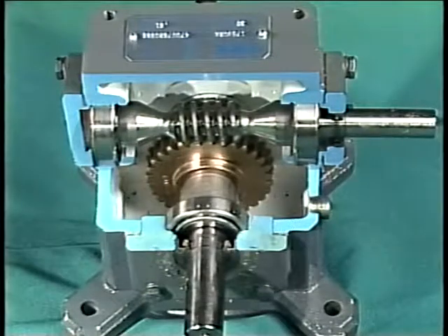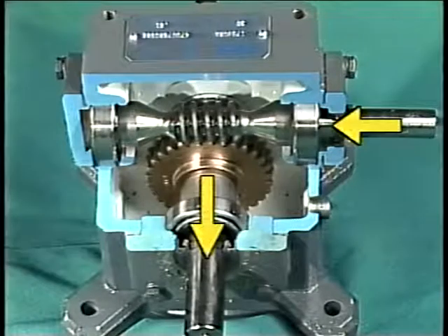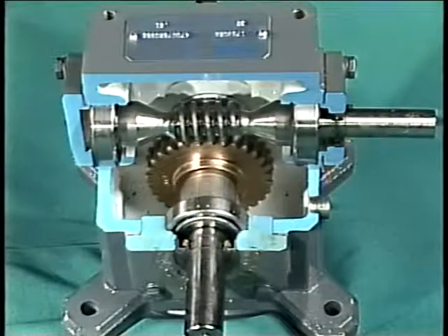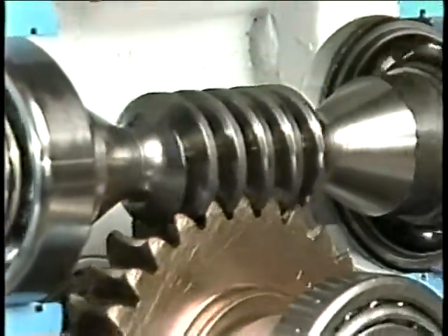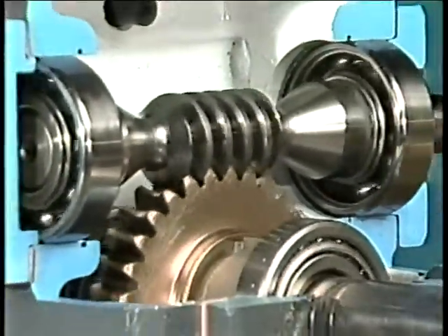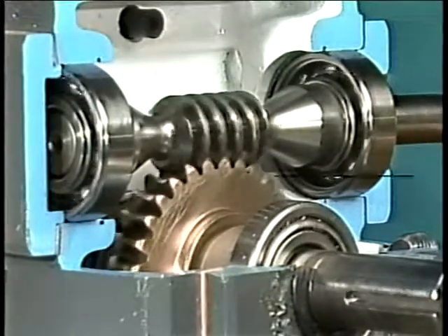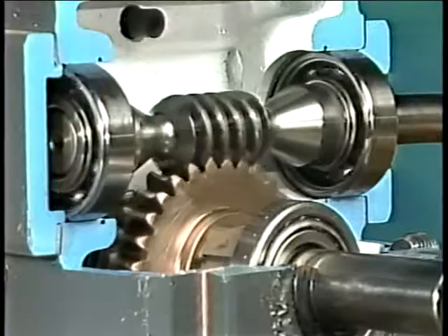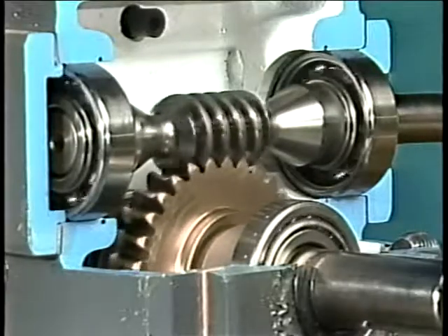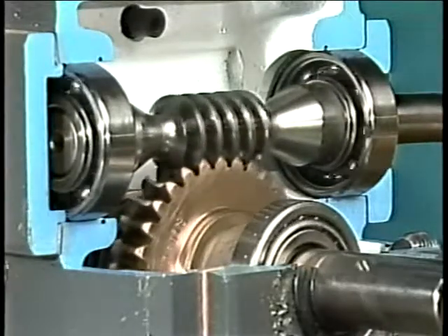Worm gear sets are generally mounted on shafts, which are set at a 90-degree angle. Power is usually applied to the worm, which in turn drives the gear. The worm in a worm gear set is considered to be the pinion of the gear set. Because a worm has very few threads or teeth, a worm gear set has a very high gear teeth to pinion teeth ratio.